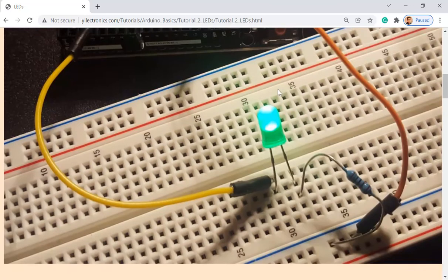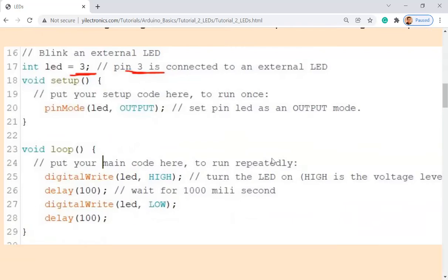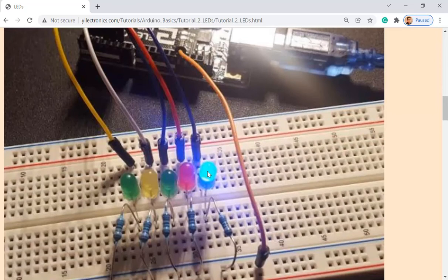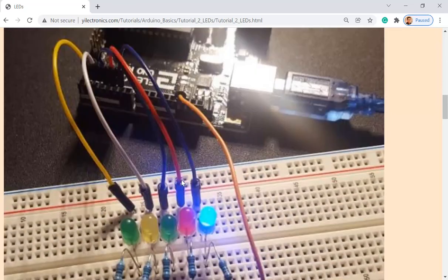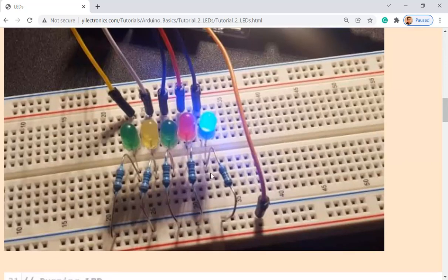Otherwise, the internal resistance of the LED is very low. It's going to draw a lot of current, and it's going to blow the LED. You can have a few LEDs being controlled by 5 pins in parallel, and you need a protection resistor for each of them.